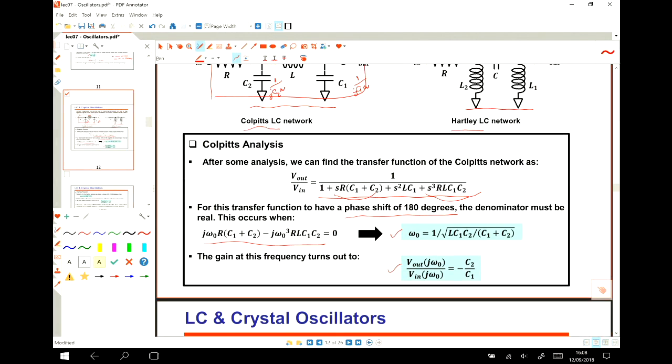And then we have to find the value for this L, so that this system is oscillating, for example, at 1 gigahertz. So this is how we should calculate all the components for our oscillator. C2 and C1 come from this, exactly 1 over K, the gain of our amplifier. And then when we define these two numbers, we put them inside this, and we know that our system, we want to make an oscillator at 500 megahertz, and then we calculate the value for L.